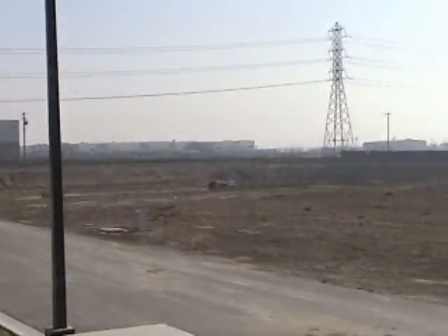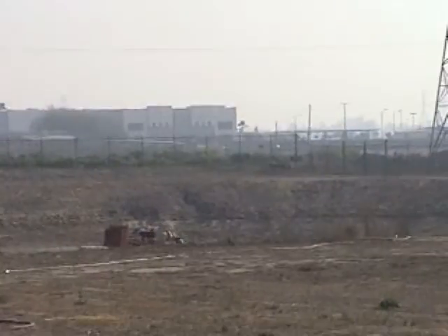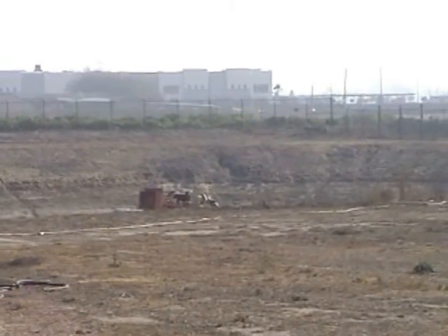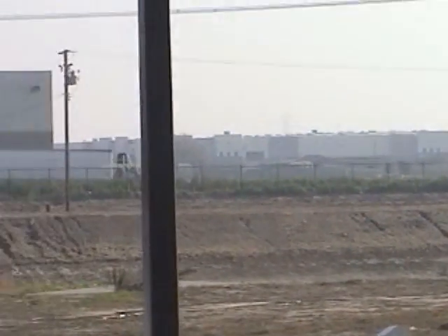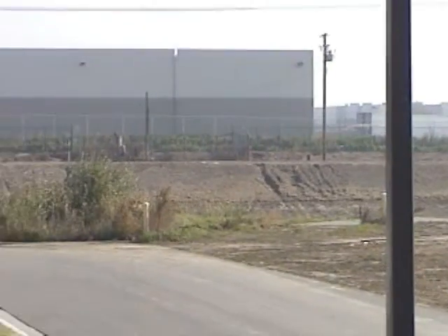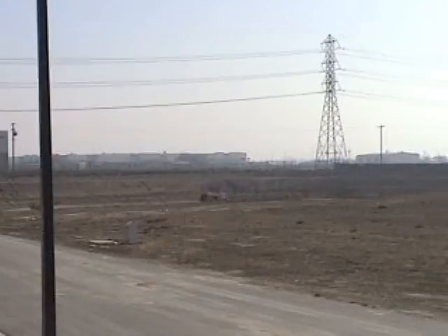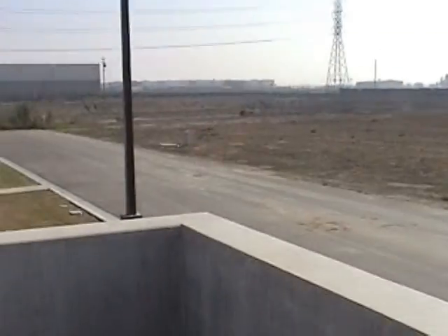So we're going to pull our final effluent. It's going to end up in that lagoon over there, and we try and keep it pumped down, so there's plenty of capacity over there. The downside of that is if it's during the rainy season, that's also our stormwater lagoon. So we want to try and keep this as low as we can, and to do that, keeping the plant online and minimizing the number of times the gate closes is really important. But to answer your question, when the gate closes, it'll overflow into that pipeline to that earthen lagoon.